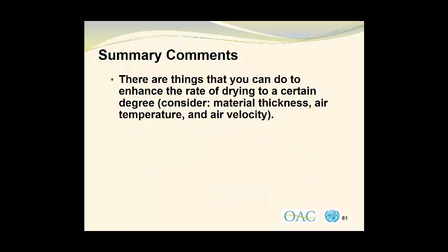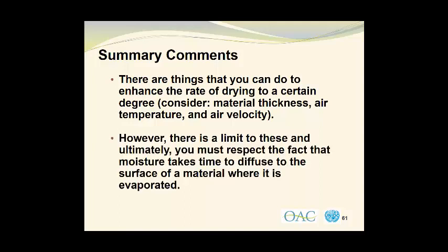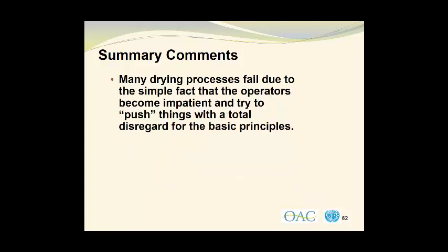There are things that you can do to enhance the rate of drying to a certain degree. You can consider things like material thickness, air temperature, and air velocity. However, there is a limit to these, and ultimately, you must respect the fact that moisture takes time to diffuse to the surface of a material where it is evaporated.